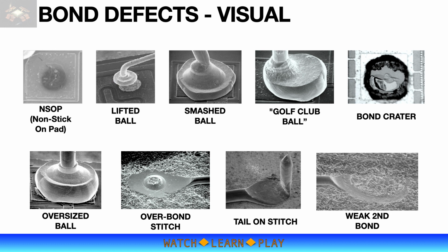About half of the capillary impression is missing. An incomplete capillary impression is an indication that transducer is not mounted properly. This will also affect first bond quality. To address the stitch shape of a weak second bond, optimizing capillary design will certainly correct the problem.